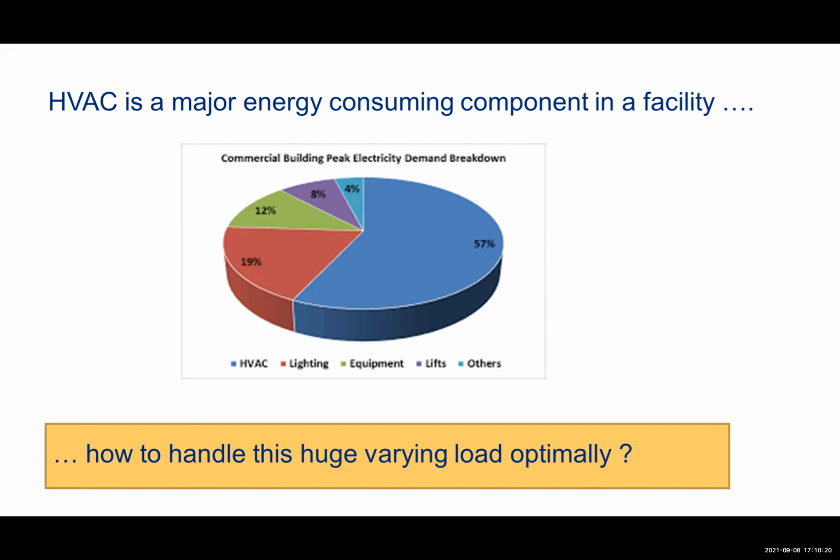You take it as 3,000 hours or 5,000 hours or 8,000 hours in a year. The heating load and the cooling load vary throughout. So the first and foremost thing that we have to have in mind whenever we are designing an air conditioning refrigeration system for a building is to analyze the heating and cooling load of a building on a complete year basis.